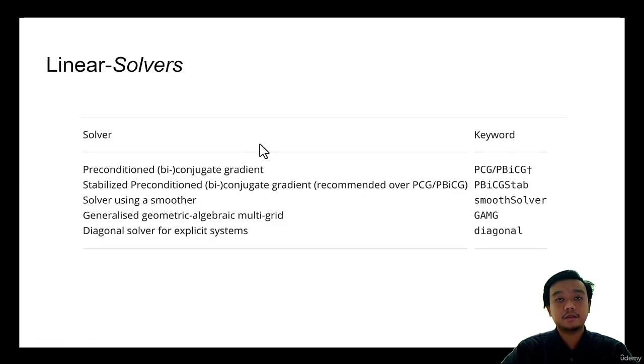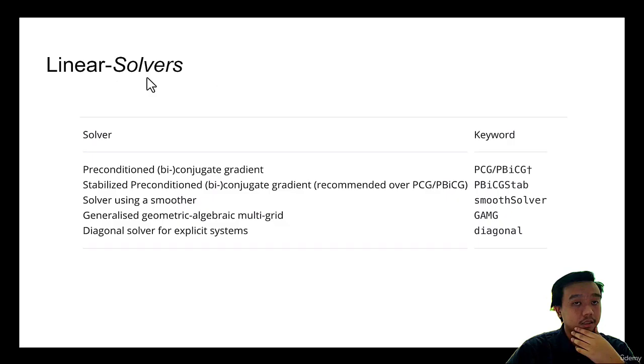And then we will discuss the solvers, but please don't be confused by the term. The solvers we use for, let's say, incompressible foam, or maybe a multiphase flow, are also called solvers, but the solvers here mean numerical solvers. In OpenFOAM terms, they are called the linear solvers. So in this linear solvers section, which is inside the fvSolution folder, we can select some